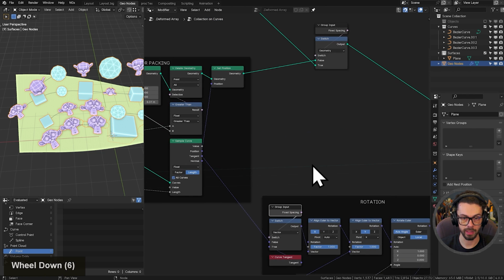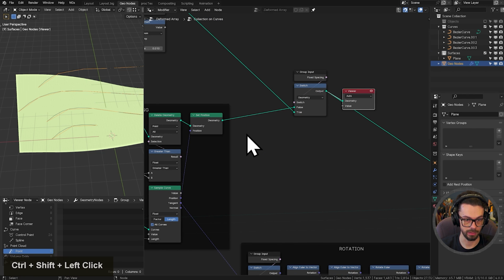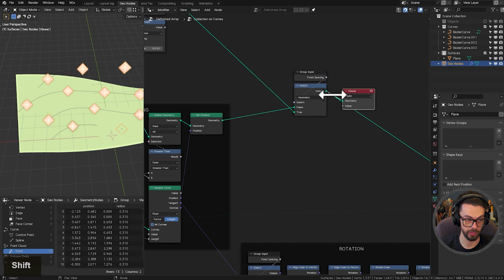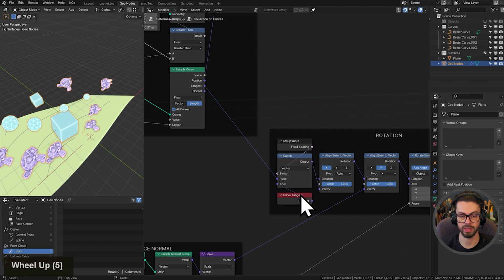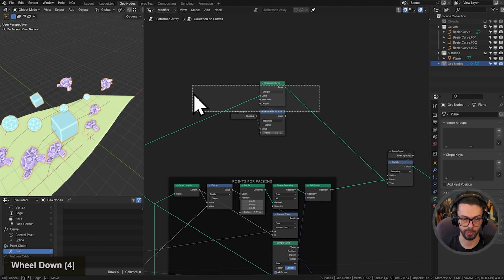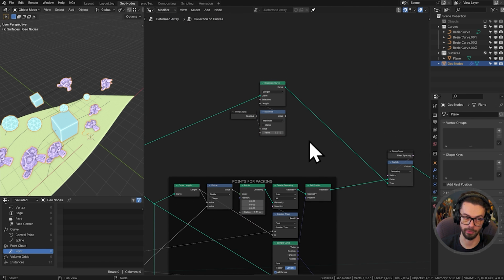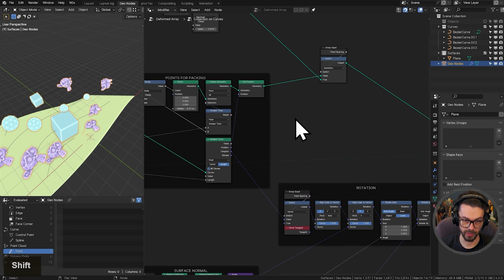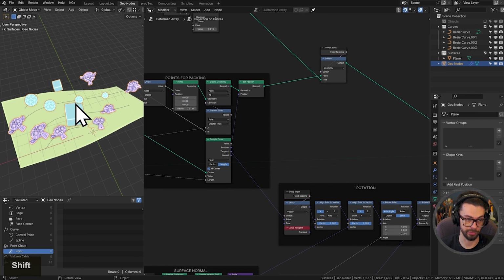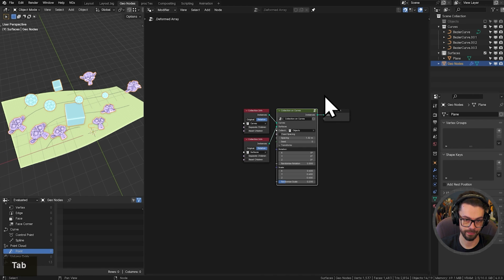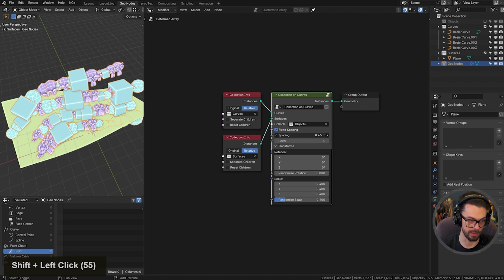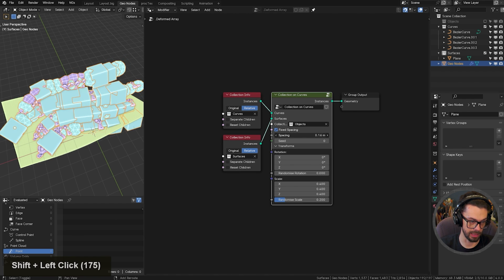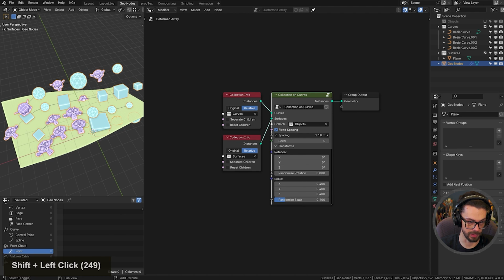And there we go. Because we're working on curves directly with this one, when we turn that off, you can see that we're actually just on points. So we can use the curve tangent directly when we're using this top branch here, which is just resampling the curves. So now we should, and do, I believe, have a correct approximation for the tangent. So let's tab back out. So when we have our fixed spacing on, if I reduce this, you can see that these are following the curve nicely there. So that's exactly what we want it to look like.